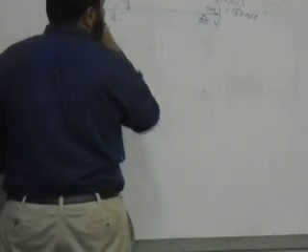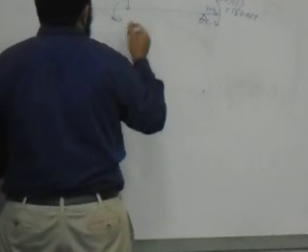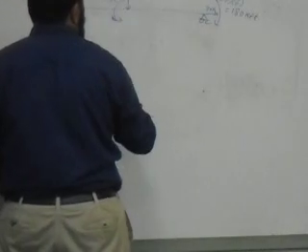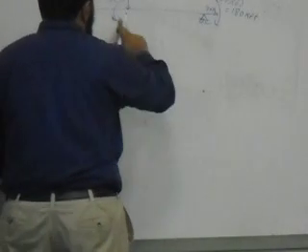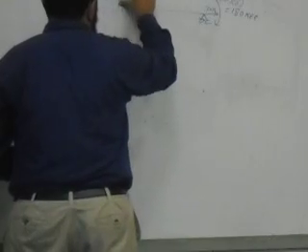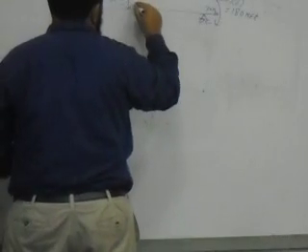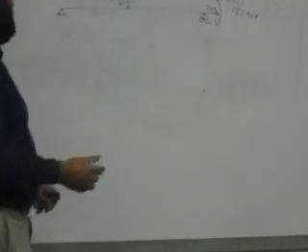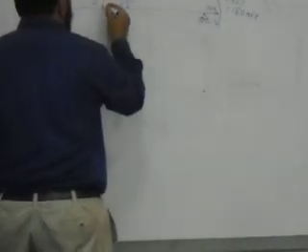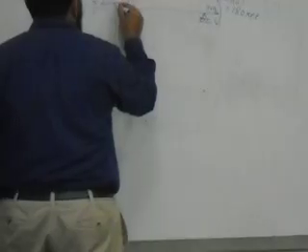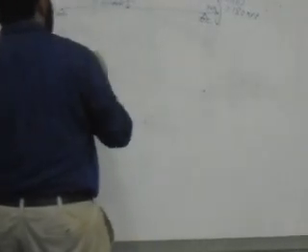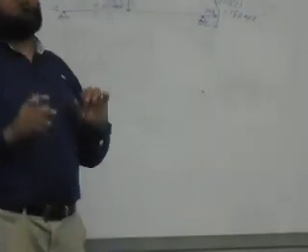Let's divide it like this so it shows better. 15 times 4, okay, so this is actually what's happening there: 15 times 4, which is 60 kip-feet, and this is point E. So in terms of the shear force diagram, the concentrated moments will not directly affect it.